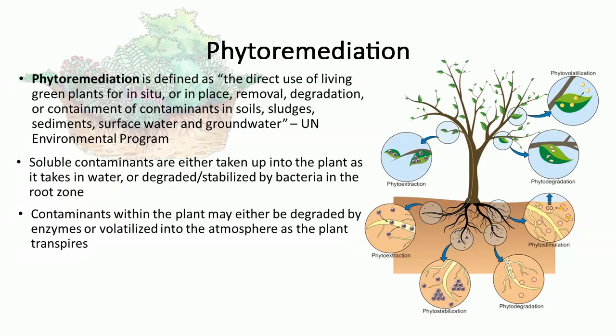Phytoremediation is currently not well understood and is an ongoing area of intense research in scientific communities. One caveat of phytoremediation is that it will contaminate the plant itself. Contaminants are removed from the water stream, but are now contained within the plant itself. This is problematic for edible plants, so it's best not to include these in a rain garden.